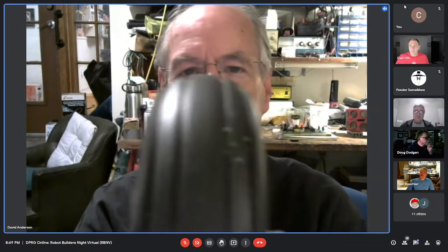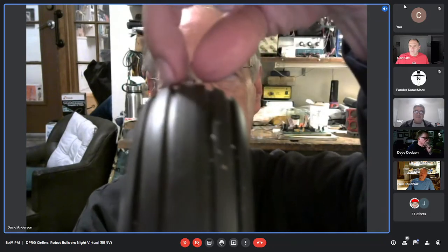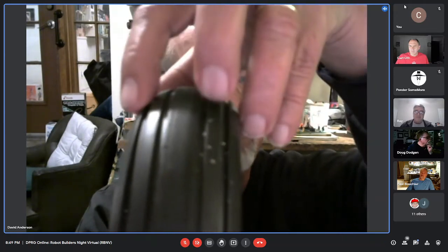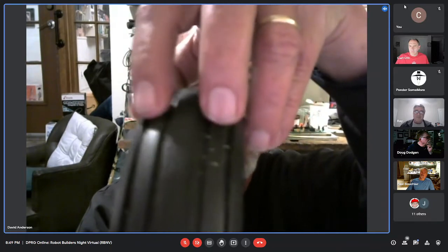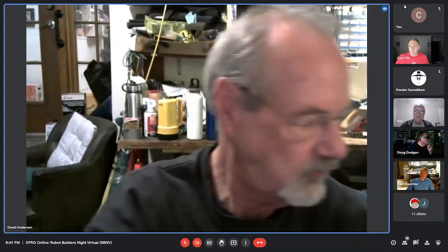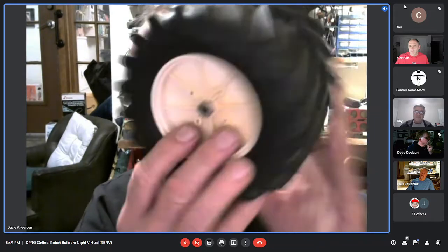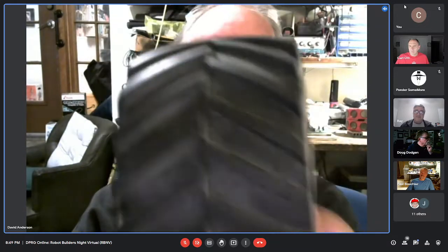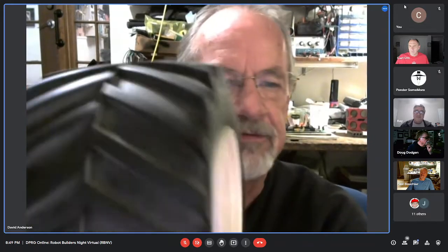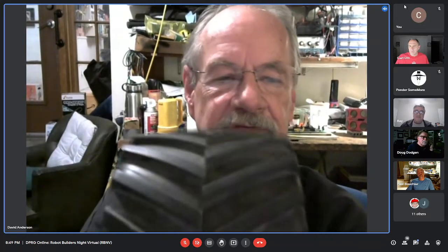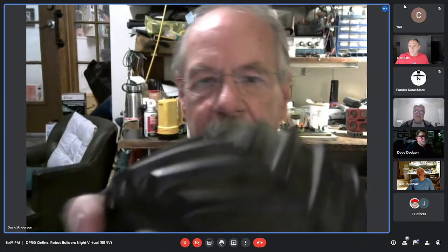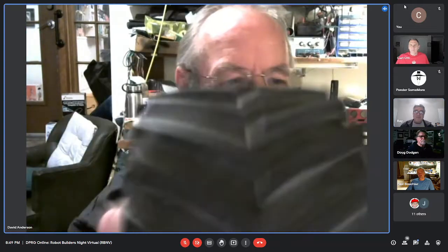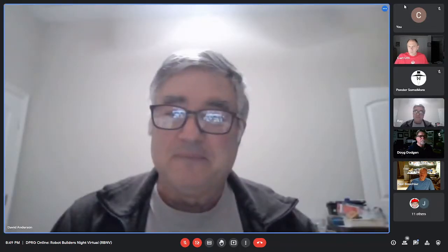It's an oval profile, but in point of fact, the point of contact, at least on a hard surface, is only about that wide. But if you sink down into grass or something, you have a wide enough surface to get some traction. The last one I have here, which we were once talking about putting the motors inside of, is miserable for odometry, both because it's so fat and flat across the top, and because it has these huge grooves. Yeah, tread bars. They try to grab hold of everything.